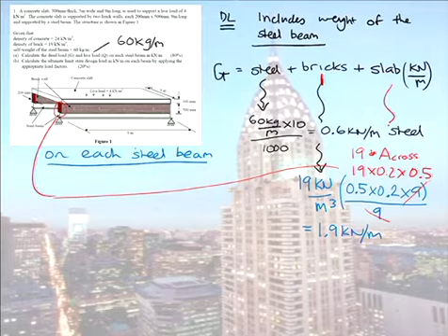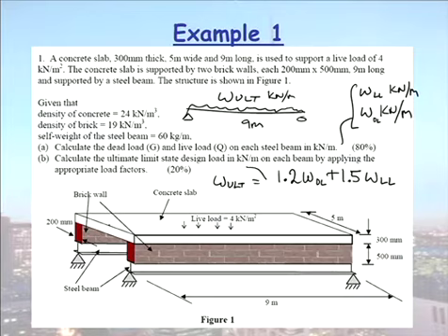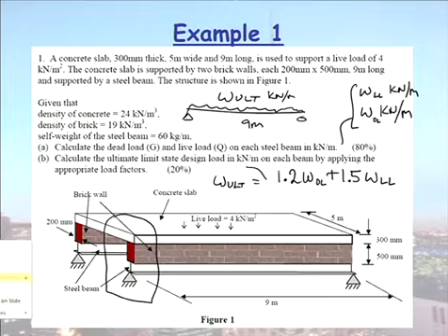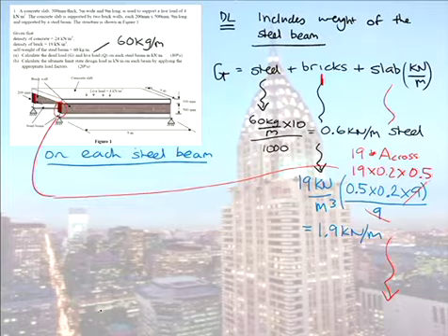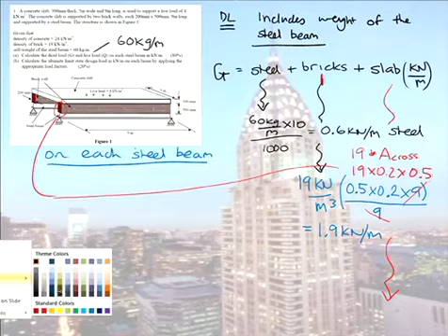Okay, then finally, we have the slab weight. So we want to know the weight of the slab on one beam. So we want to know half. So if you were doing it the quick way now, you would, in terms of cross-sectional area, just look at the cross-sectional area of half of the slab. So here, and it keeps on changing the colour when I jump slides.